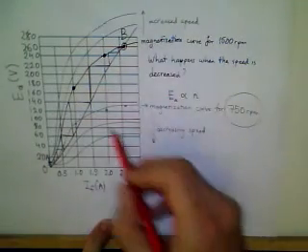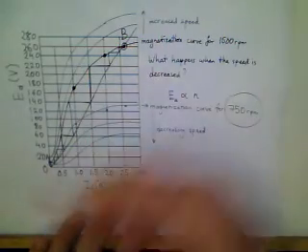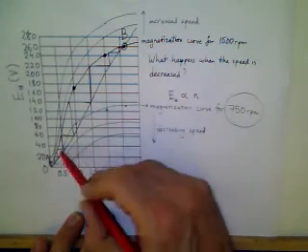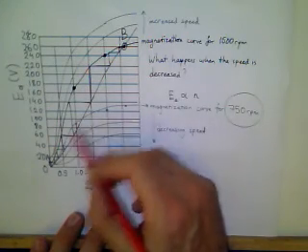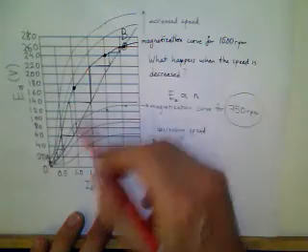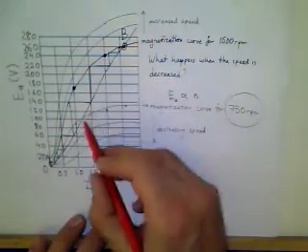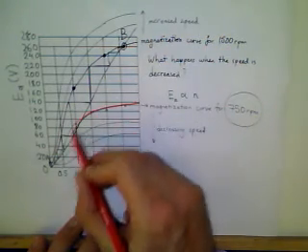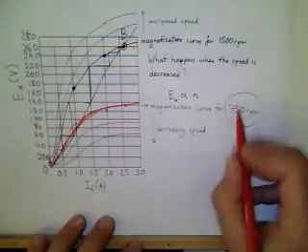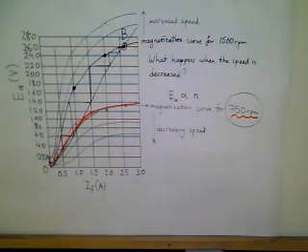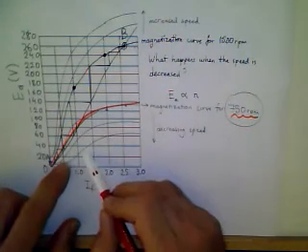the linear portion of the magnetization curve for the dropped voltage will be below this line. So there's a kind of limit for the decreased speed. Again, with the graphical reading errors, we assume that this is the curve which is the critical load line slope for 100 ohms field resistance. So the speed for this curve is roughly the half speed, which is around 750 RPMs. At lower speeds, this machine cannot self-start.